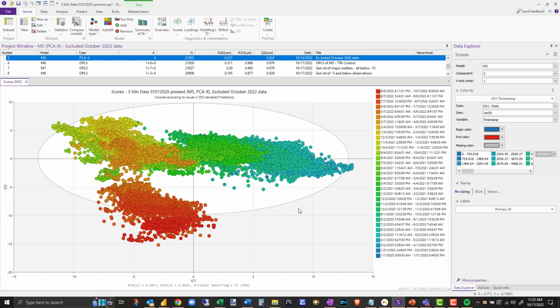One of the things I always get concerned about is when you see so much data that you have to pull out, where you have IO timeout, configure, bad input, all those kind of things. There was an awful lot of that in this data set, and you could see it in the missing data. You start to wonder, is the information I'm being given from the process even valid?